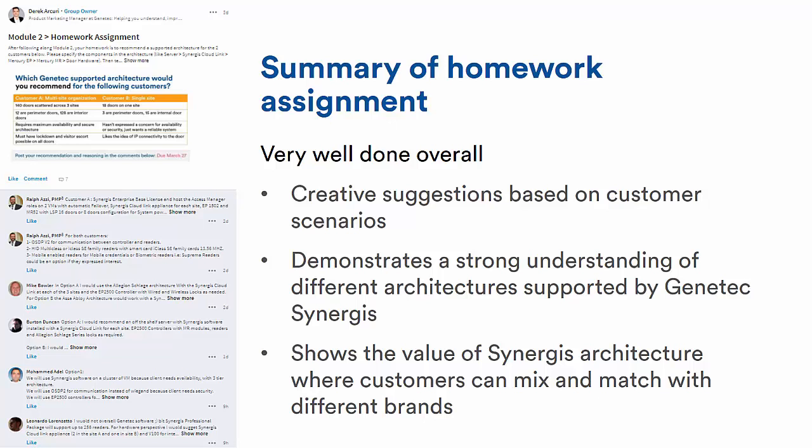The second customer is a single site, small installation with rather simple expectations. They just like the idea of IP connectivity to the door, as they know the installation would be less expensive. The recommendations that were made were great. I've seen Access A1001 PoE controllers, HID Edge Evo PoE controllers paired with IP locks from ASA Abloy.